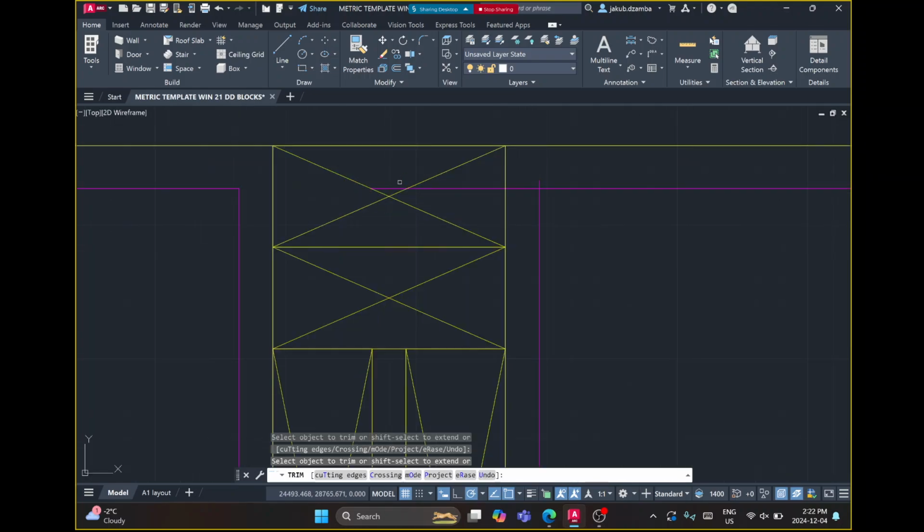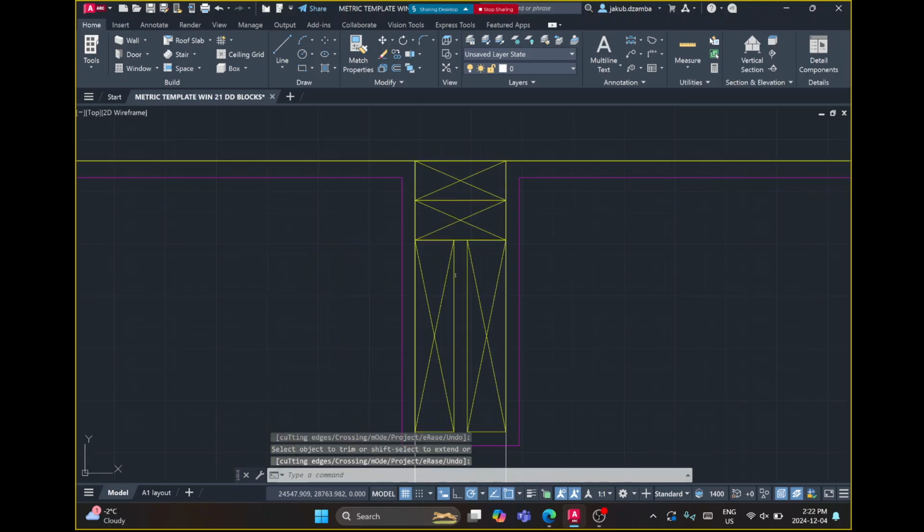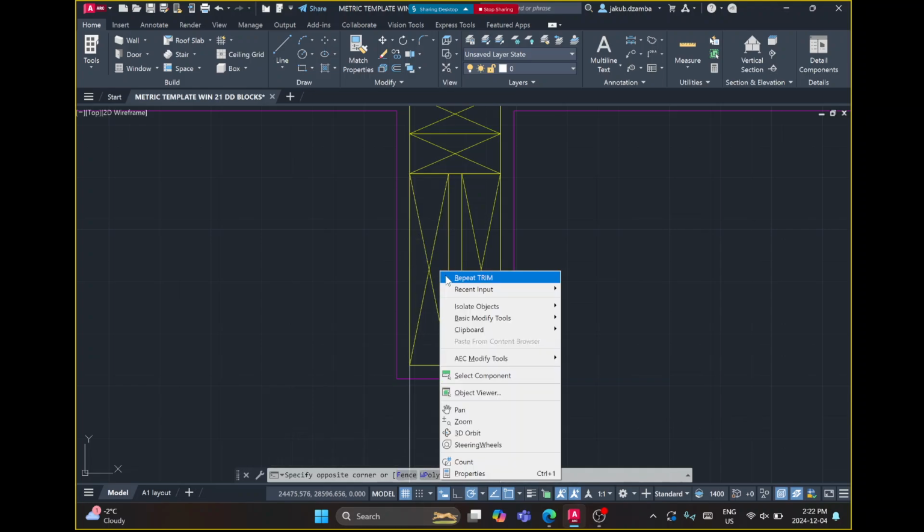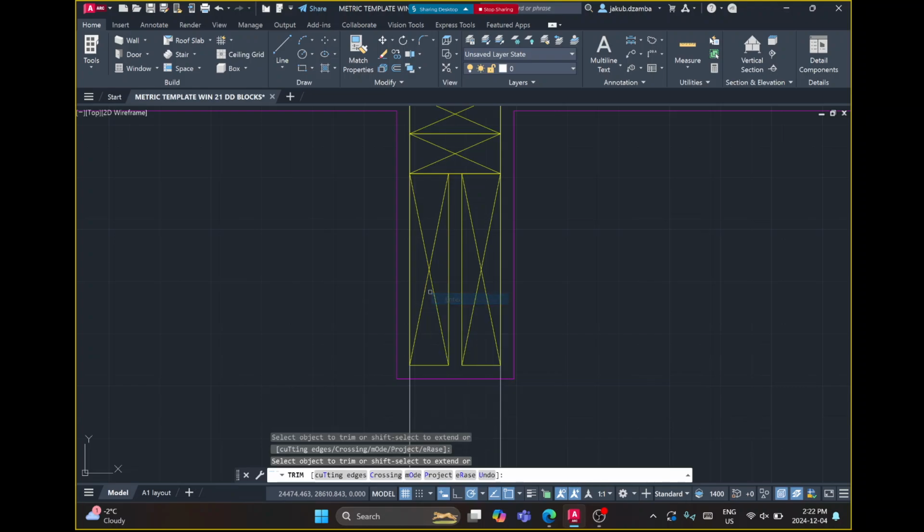I'll clean up the drywall a bit so it connects properly. And over here it looks like they don't have 2x8s, they have 2x4s. So I wonder if instead of drawing them again, if I could just do something like this. I'll just offset by 89 and adjust it.